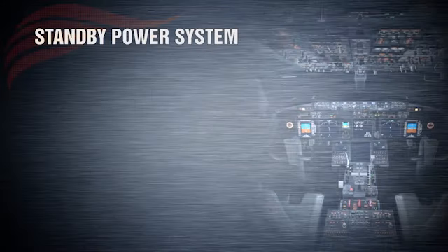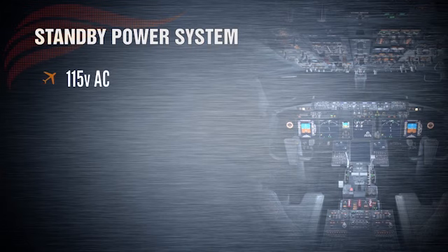We've already mentioned the word standby a couple of times during this lesson. For example, in the AC buses section, we talked about the AC Transfer Bus 1 powering an AC standby bus. The standby power system provides energy only to essential items in the event that both engines and the APU were unavailable or faulty. The standby produced power is 115-volt AC power and 24-volt DC power.